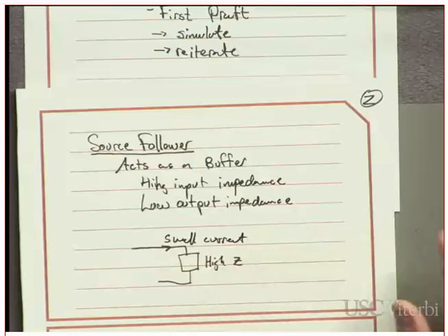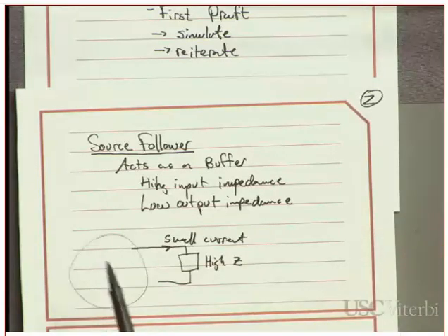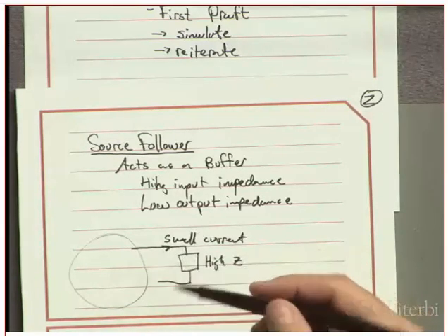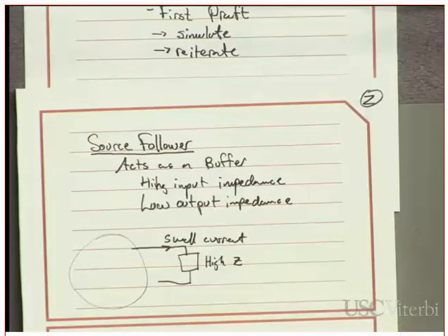And a small current draw basically helps you not disturb the circuit over here, right? So when you design, say, an amplifier, you design it with maybe some load impedance in mind, and putting something that has a high impedance in parallel with that load impedance that you designed in there basically won't change the load that it sees much, right?